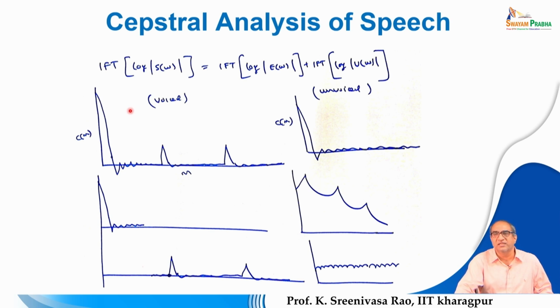As I mentioned, in case of voiced speech, the reasonable value for p will be between 8 to 15, let us take 12 for example. Therefore, in the cepstrum domain, the number of samples to be considered will be close to 18, that is 3 by 2 times, or 1.5 times, the generic LP order.